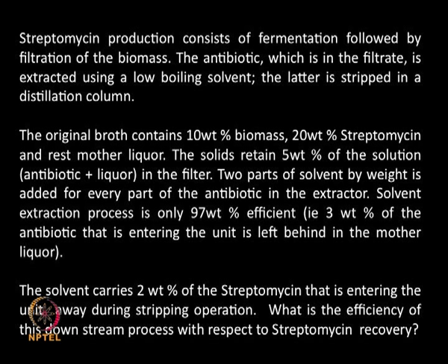Then it goes to the extractor where you are adding some solvent and extracting your antibiotic. The extraction is not very efficient because 3 weight percent of the antibiotic that is entering the unit is left behind in the mother liquor. That means only 97 weight percent of the antibiotic entering the extractor is taken up by the solvent, and 3 weight percent is left behind by the mother liquor. So we have lost 3% here.